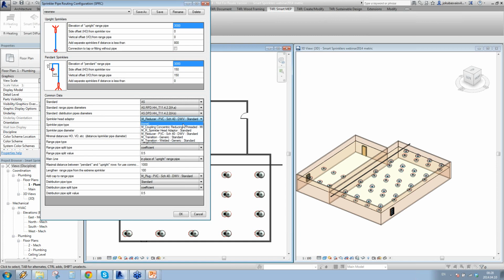All these families, all these names, and all these connections come from your project. If you load some families in the project, they will occur here. It is really easy. You place the families, you take the information here. Also, you have to create some different pipes.